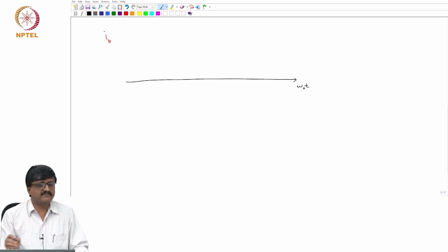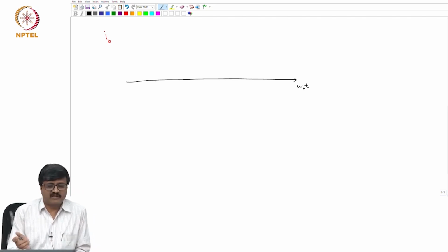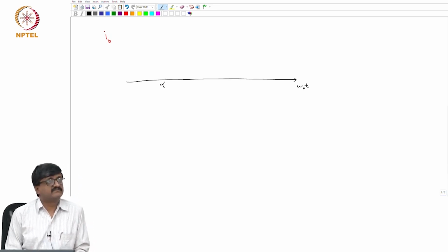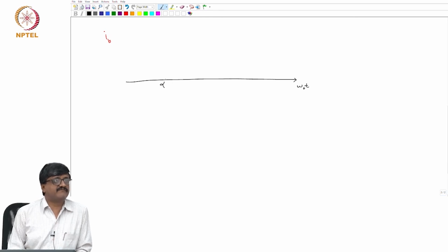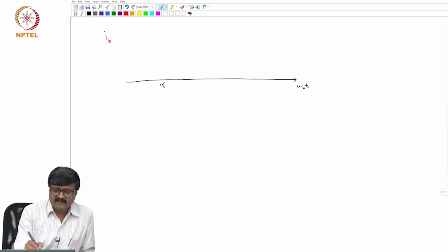What is the instant or angle? We are actually considering a more general operation where it is not diode operation. Alpha. So, at alpha, thyristor valve 3 is turned on. So, if thyristor valve 3 is turned on, then at alpha, IB is equal to ID.